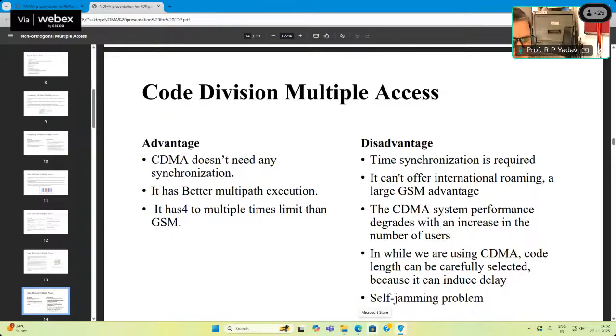And so the signal ratio that you have to provide to each user can hardly be maintained. That's why some calls may drop, and user satisfaction with the service will obviously not be good if the number of users becomes more than that at which a minimum signal to noise ratio based service can be provided to every user.